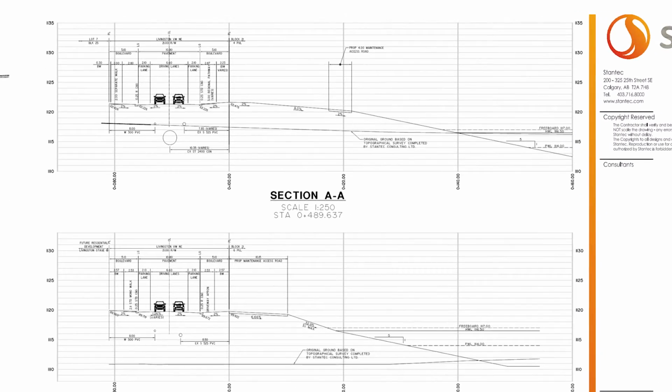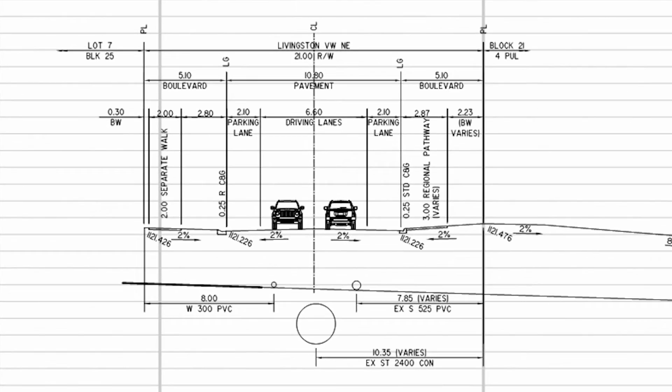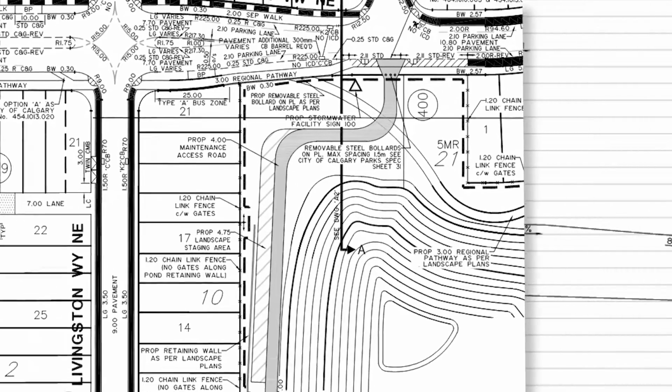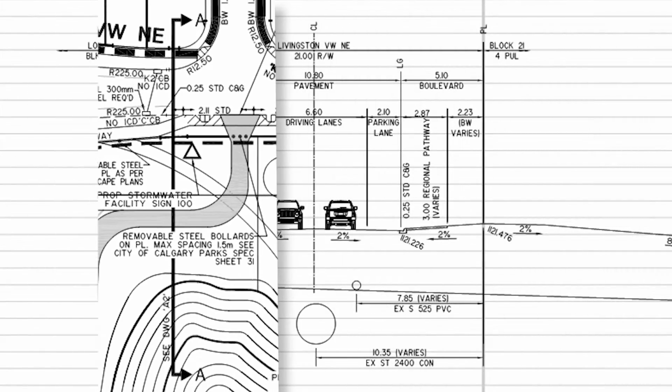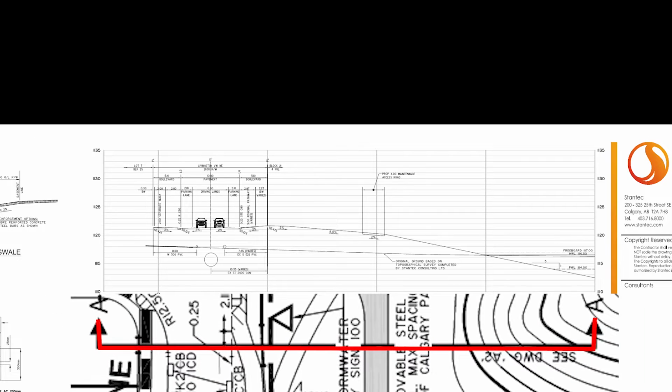We also see several cross-sections, but this time referring to the road. The cross-sections here give measurements of road width, concrete structures, road and shoulder slopes, as well as some underground information. Note how they are labeled and how they are represented on the drawing. The arrows show the orientation of the cross-section, which is helpful if the road isn't symmetrical.